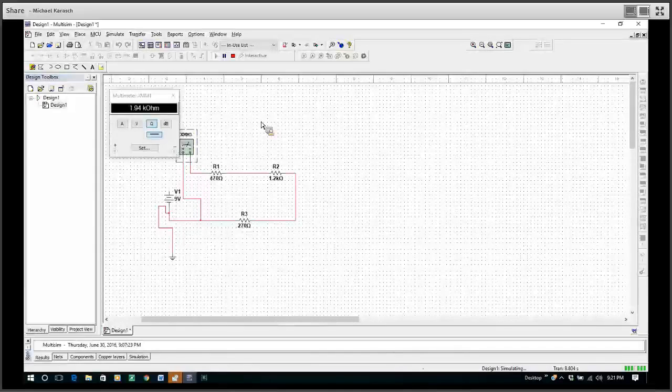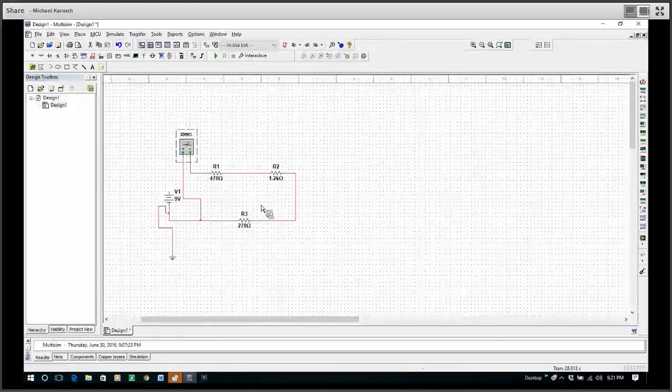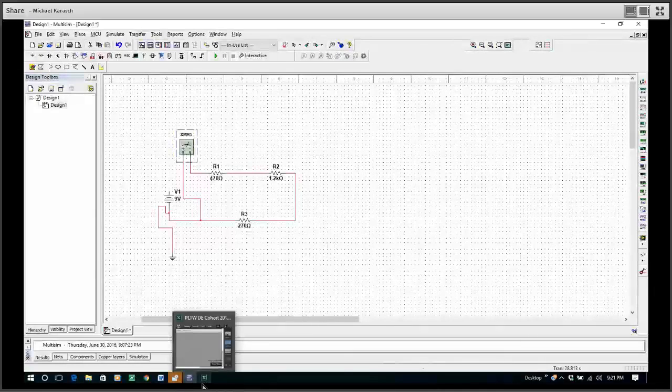So, anyway, that's how we use our Multisim. That's how we build these circuits. That's how we insert the meters. Especially when you're doing total resistance here, you want to disconnect the power supply. Don't forget to change your battery voltage on these, and make sure all your resistors are the same. Parallel circuits are not that much different. So, all right, thank you for watching, and hopefully you'll have a successful activity here with 115A through 115C.